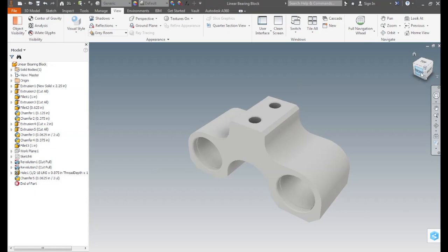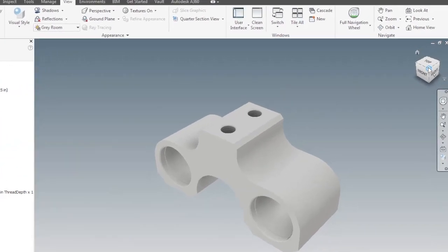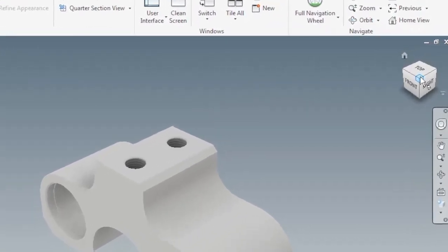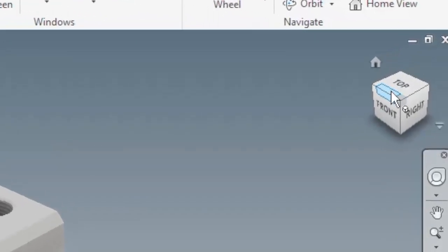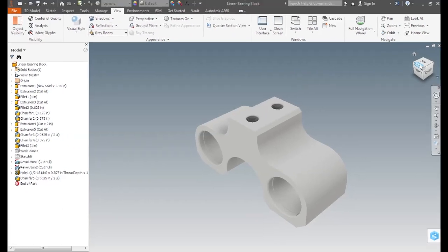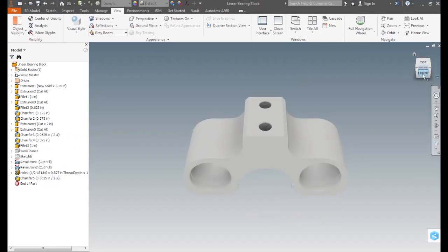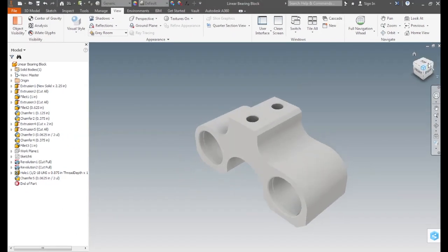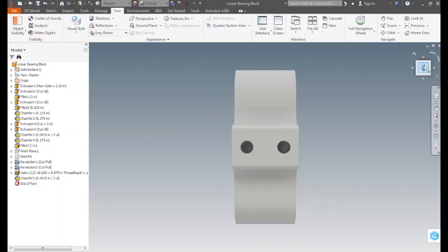The first navigating device we are going to demonstrate is the view cube. We can find it at the upper right corner of the graphic window by default, and it is partially transparent when inactive. As we can see, you can turn the model to isometric view by clicking the cube corner. One can click an edge for an edge on view, or a face for an orthographic view of the model.